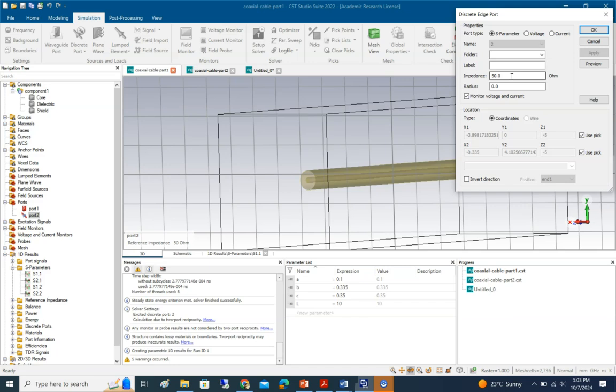How about using those short circuit and open circuit concepts in here? Theoretically, for a short circuit the resistance value is 0, and for the open circuit case it is infinite. But we cannot put a 0 value in CST, nor can we put an infinite value. However, we have a solution.